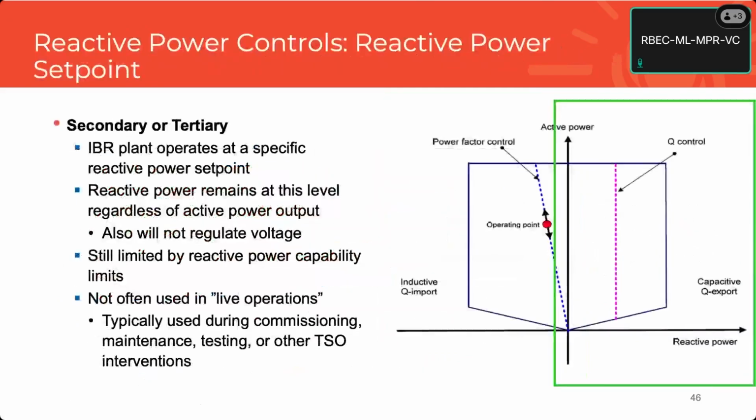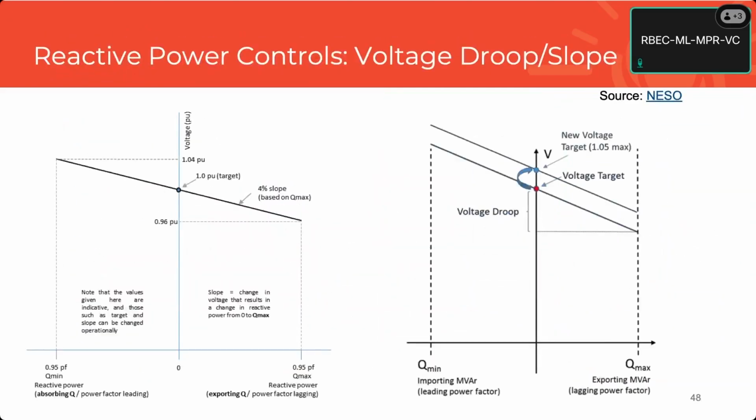Let's go to voltage control Droop for the same. This is going to be exactly the same concept, but this is a little bit more straightforward. So power frequency and voltage reactive power is the same exact concept for Droop. In this case, we've got the same kind of plot, but now left to right, we have reactive power. Inductive on the left side, and in this case, capacitive on the right side. And this one is voltage. So now voltage is the measured input. So we're measuring voltage, and the controller is going to act on the reactive power.